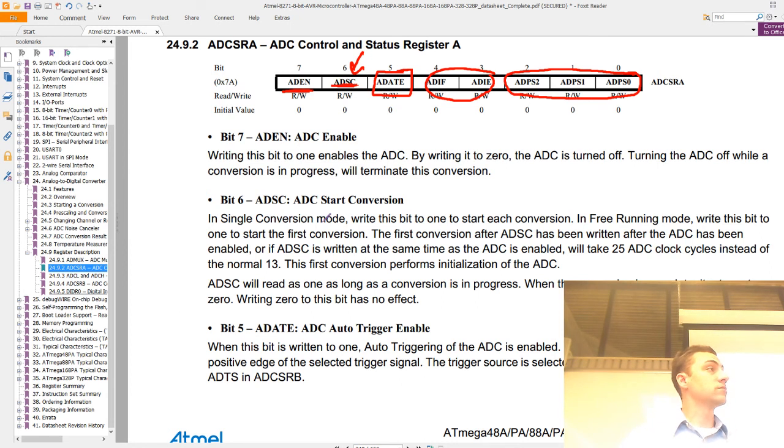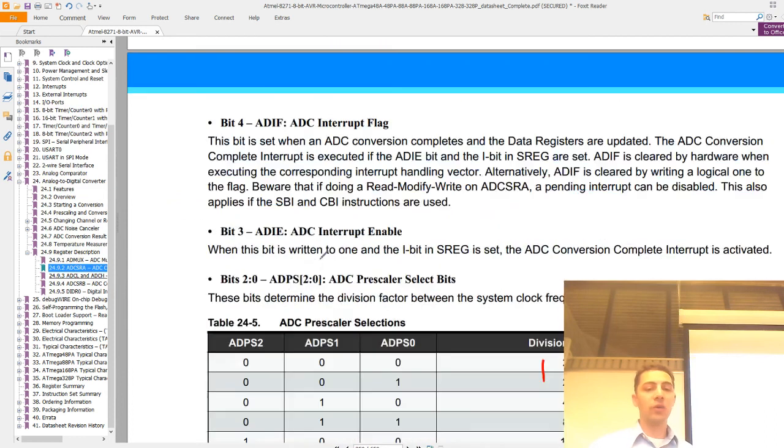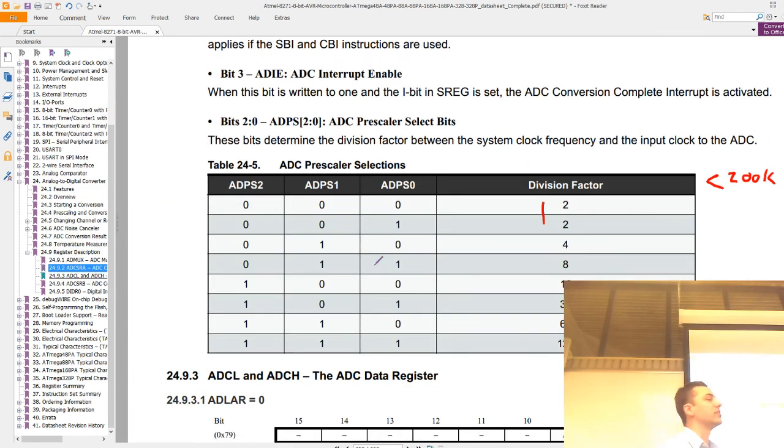Can we take these tables right off something, paste them and print out? So you get a page double-sided. I would suggest that you build up a little Excel sheet, because the tables that come out of the datasheet are stupid big and wasteful. Look at all that wasted space. You don't even need this title. Division factor, okay, we get it. So shrink this down. You don't even need to list out all 3 bits; 0 through 7 is really all you need. So build it yourself. You can fit a lot more nicely.